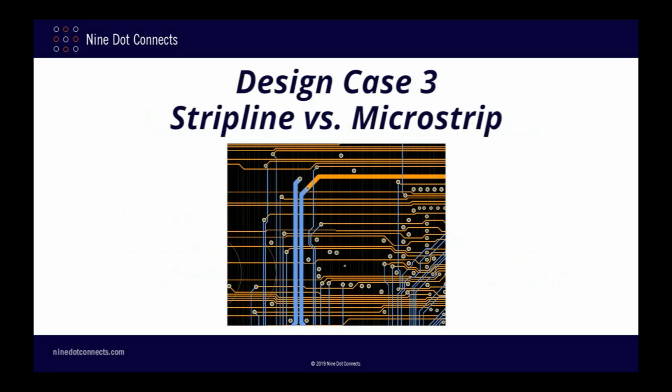Back when I first started doing PCB layouts, which was more years ago than I care to think about, the choice of routing on an inner versus outer layer was purely based on convenience. I just picked whatever layer had the space for that trace. A common routing paradigm was to put mostly horizontal traces on one layer and mostly vertical traces on another. And the use of solid copper planes was merely a convenient way of connecting power and ground. Just drop a via anywhere you needed to connect to a power or ground rail.